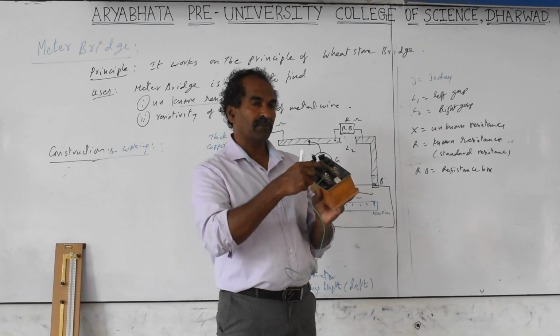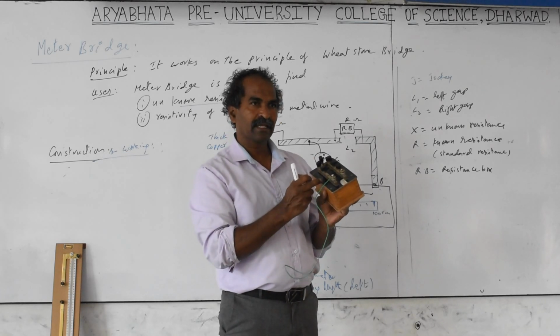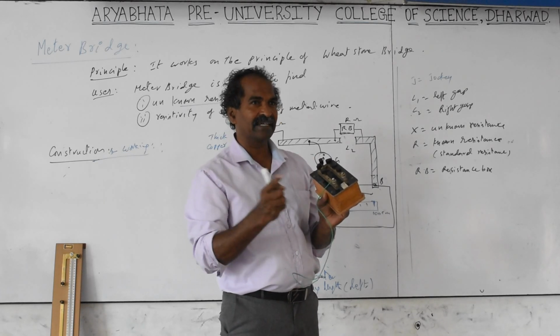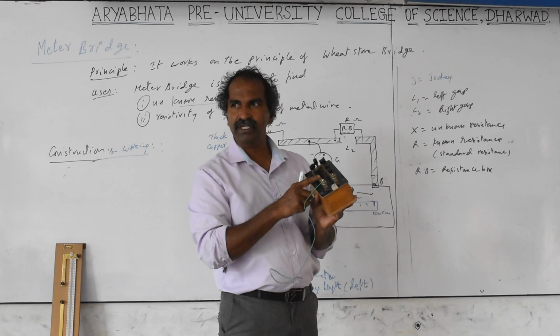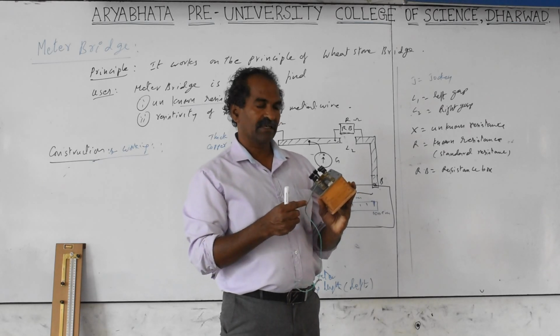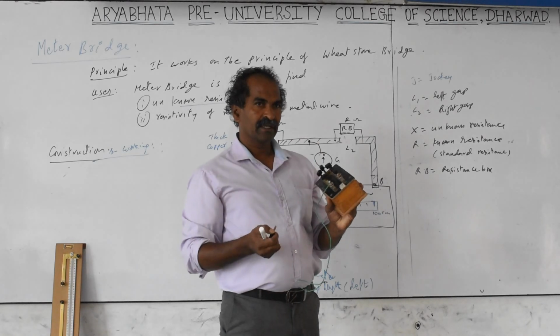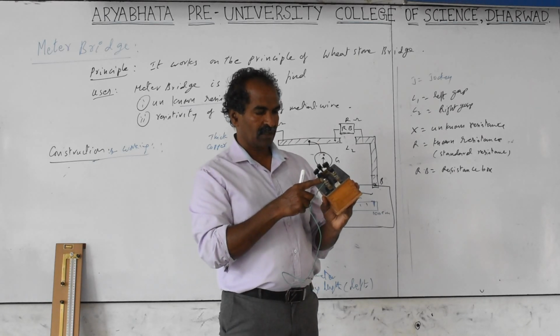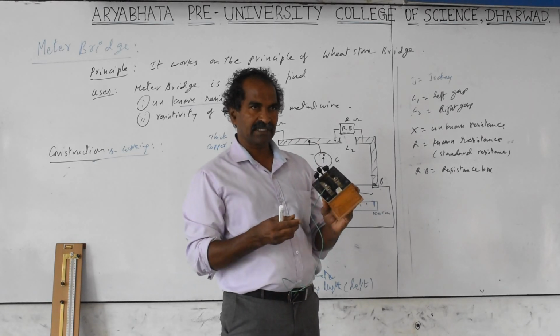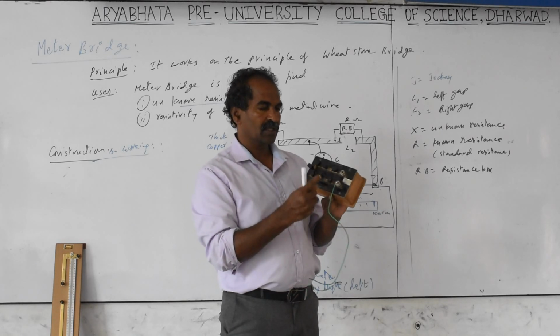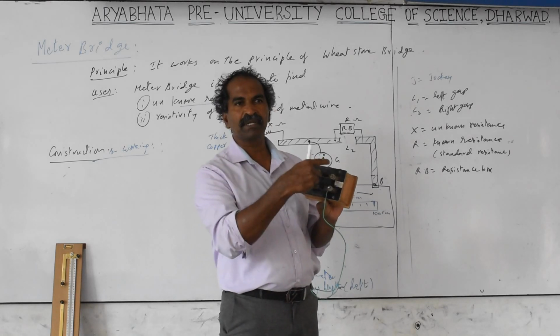1 ohm. If you remove the next one, this is 2 ohms written here. That means if you remove 2, all are in series and added. 1 plus 2 is 3. If I want a 7 and remove the 5, this 5 plus 2 plus 1 is 8. I want 7, so you only close 2 and 5, and the total resistance will be 7.